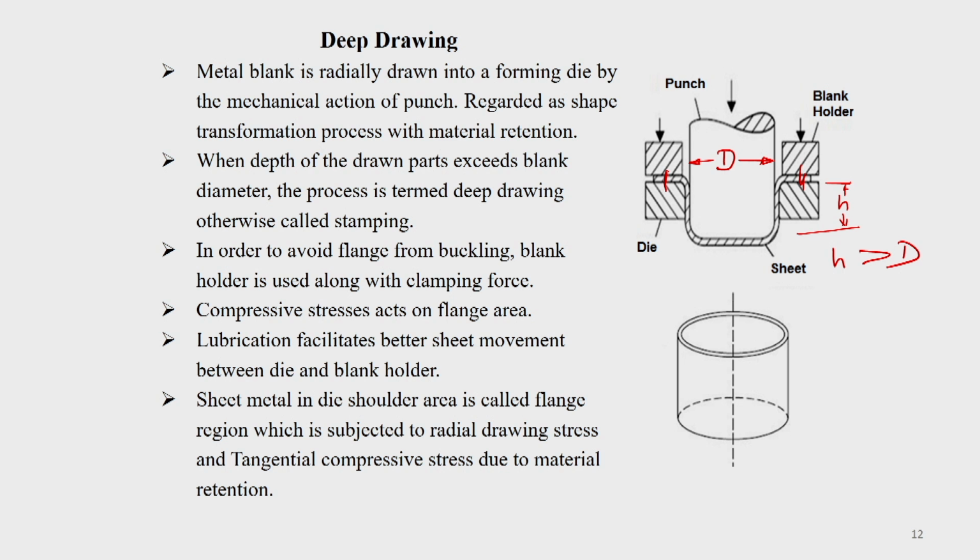In this deep drawing operation, lubricants are generally used, so that it gives a better sheet movement between the die and the blank holder. Even between the punch and the blank also, you should know that. So, these things are there. Okay.